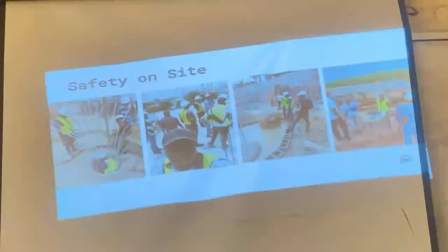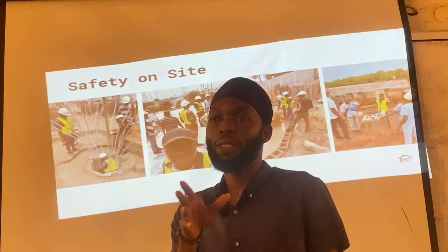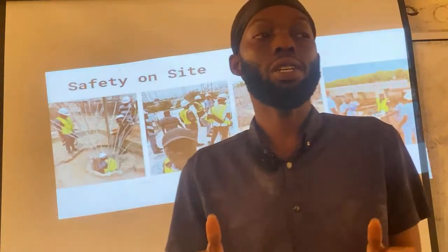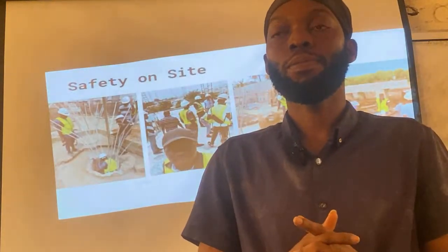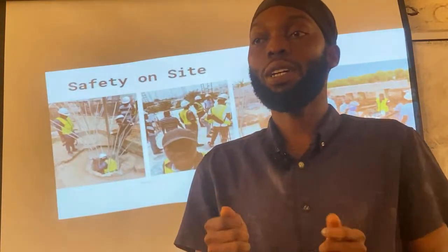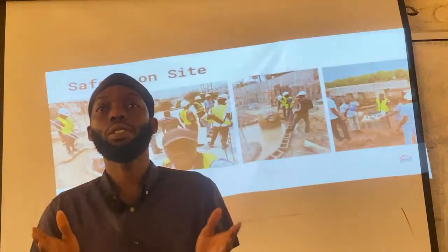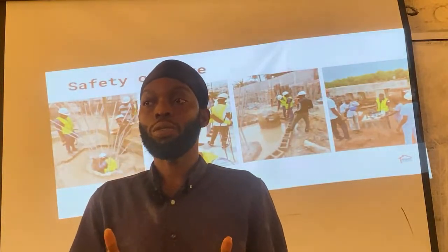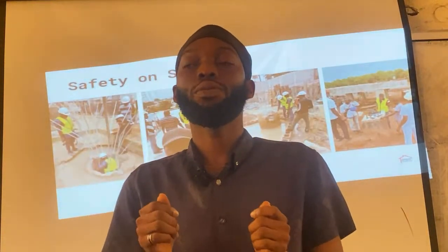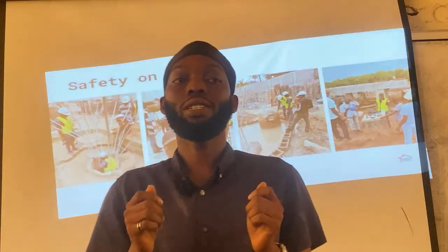Good afternoon, everyone. My name is Engineer Yemi. I would like to shed more light on what you asked. Concerning the size of the columns or the size of the structural element, there's something we call the distance. That's like the depth, or let me say the distance between the transducer and the receiver. So fundamentally, in a normal sized column, probably a 250 by 250 mm column, we've already located where the rebars are. So we, as CAB, use 120 mm to be the distance between our transducers, where we are using the indirect method.